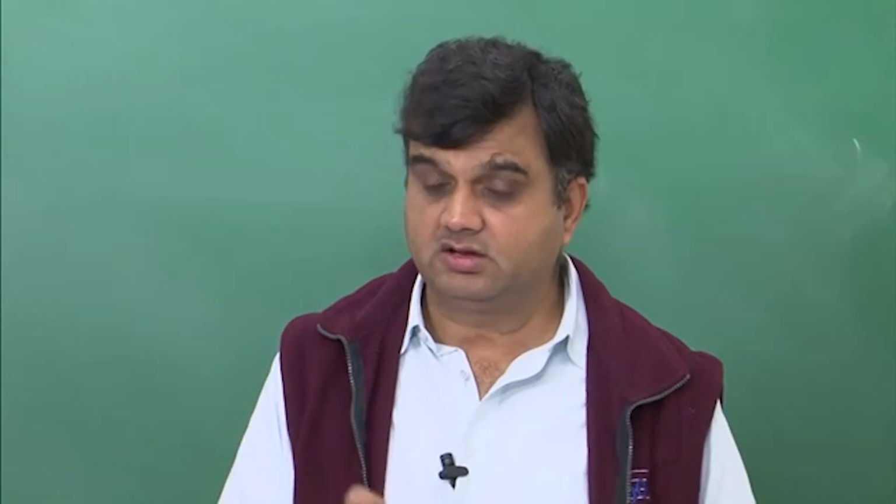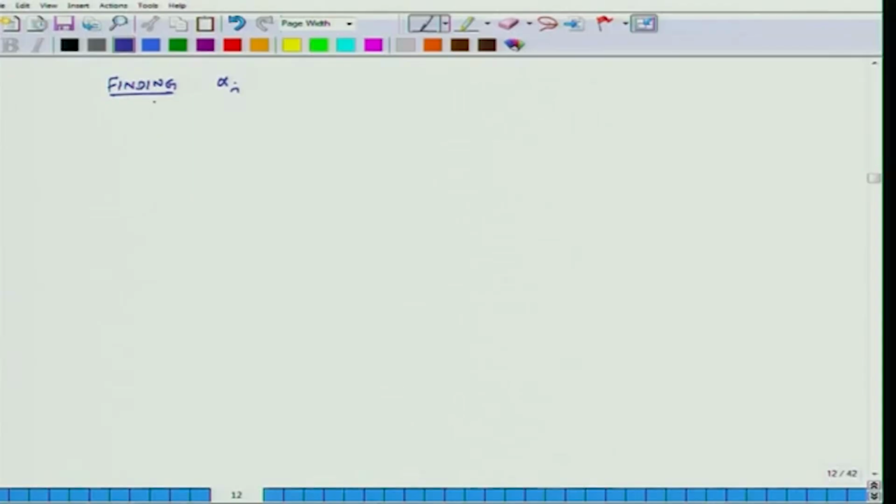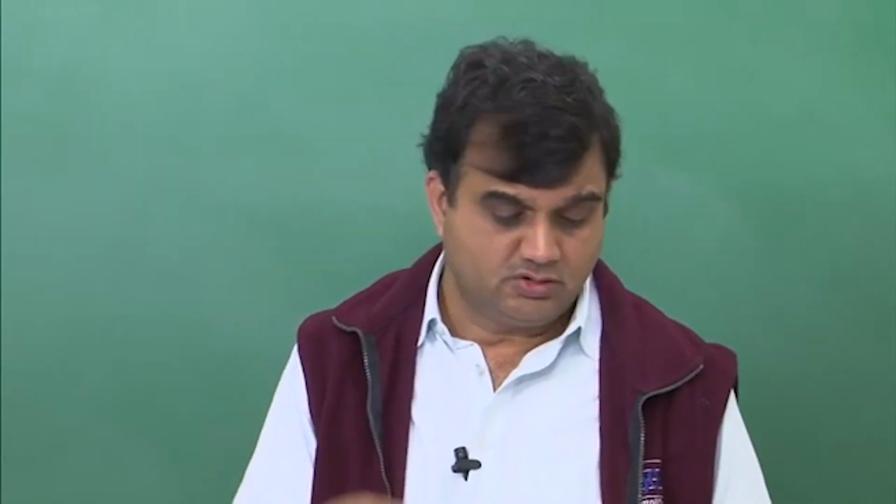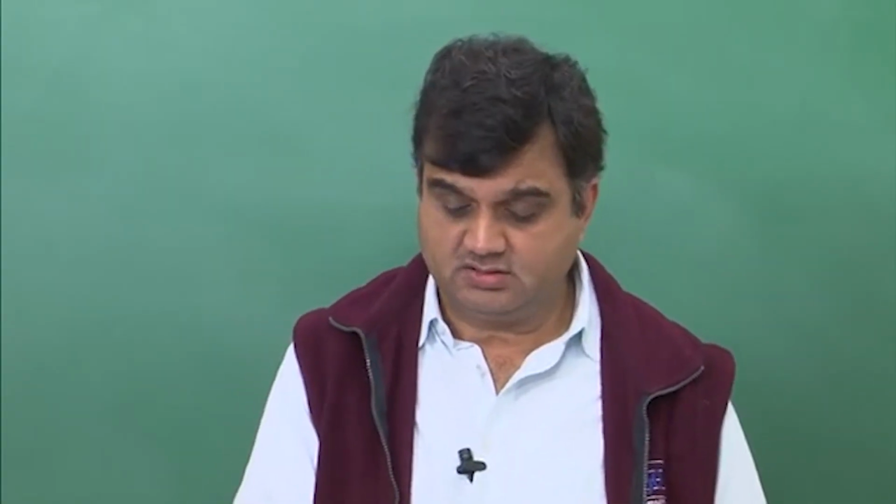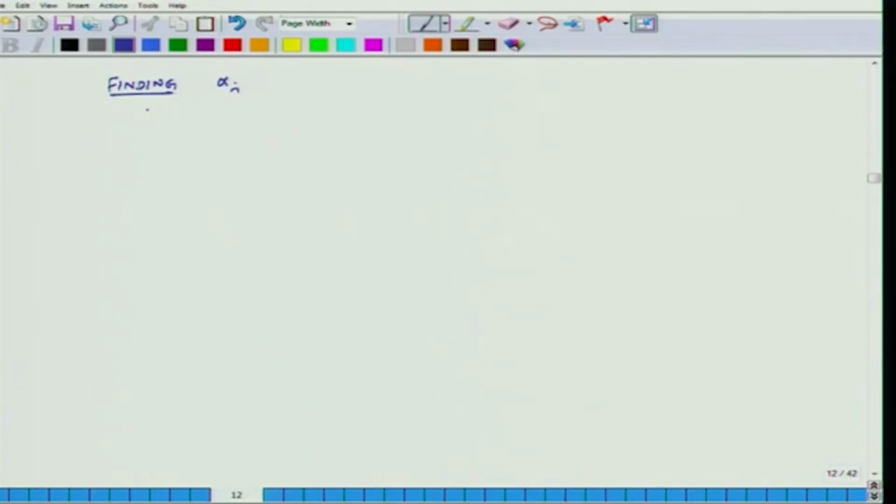One thing to understand is that alpha is the absorption coefficient, and we had discussed earlier that it can change with frequency. So typically we identify alphas at 5 or 6 standard frequencies. Finding alphas, the standard frequencies at which you measure them are 125 Hertz, 250 Hertz, 500 Hertz, 1000 Hertz, 2000 Hertz and 4 kilohertz. At these different frequencies you try to figure out their values.